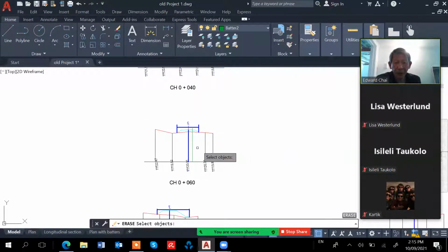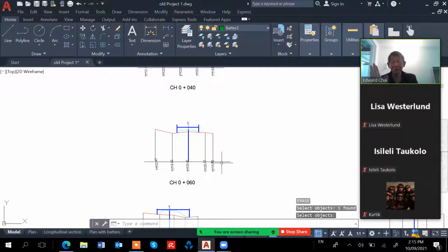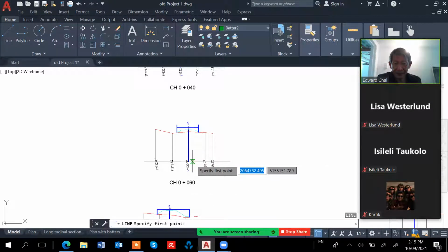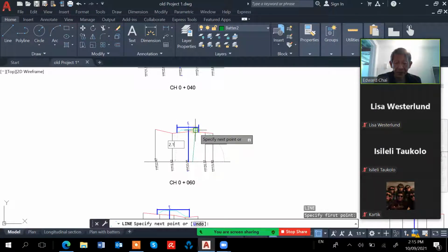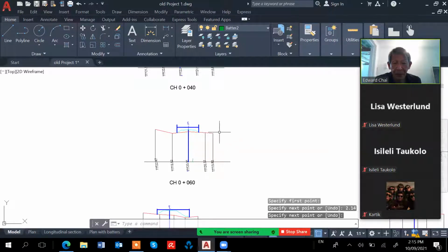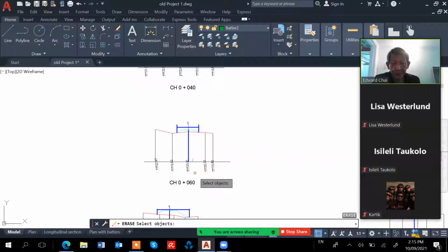So if your cross section is flipped to this upright position, then you could use a line. Otherwise, you can use the offset. If you maintain the slanting orientation, then you use the offset to do it. So for example, I try again, 22.14. It should be line 20, just type 22.14.